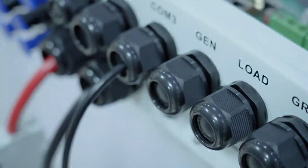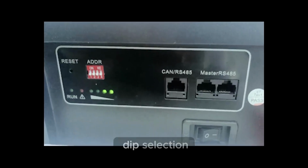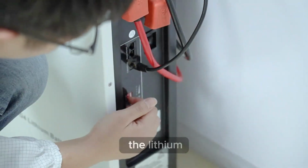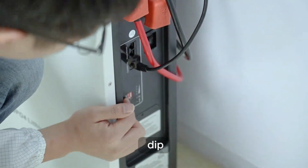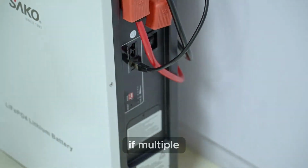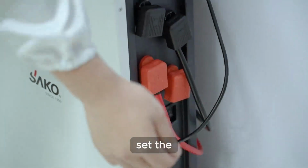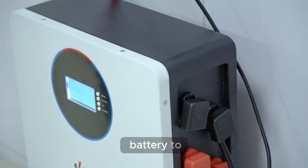Step 5. Lithium battery dip selection. If the inverter is only connected to one set of lithium batteries, please set the lithium battery side dip switch to 1. If multiple batteries are used in parallel, set the dip switch of the second battery to 2, and so on.